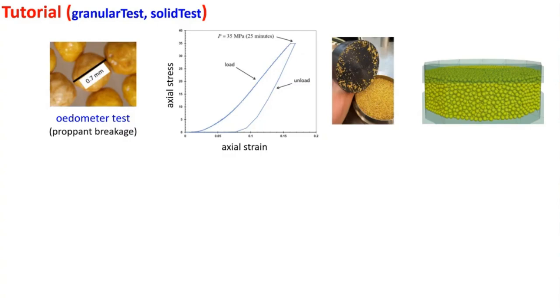So what do we do in principle? We just take the system that we had and add one new thing, a wall, and give it a velocity. Then we hook up the ability to monitor the stress and the strain as this thing pushes. In PFC, there's built-in ability to not only monitor things, but also plot them like this. Everything's going to be in PFC.